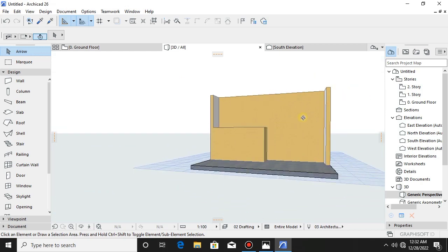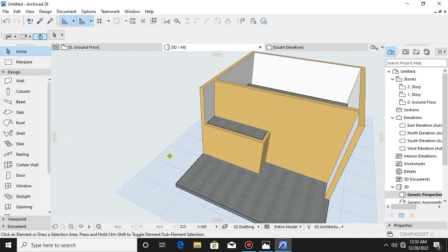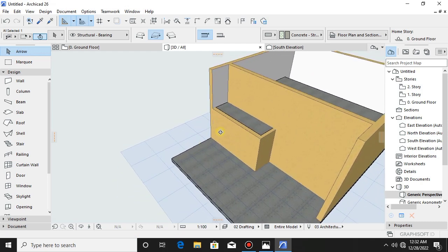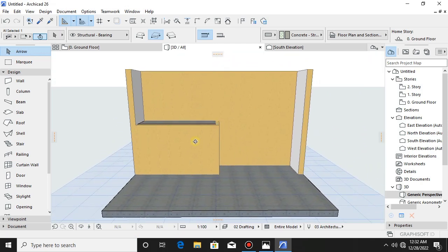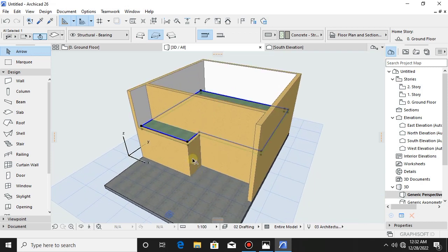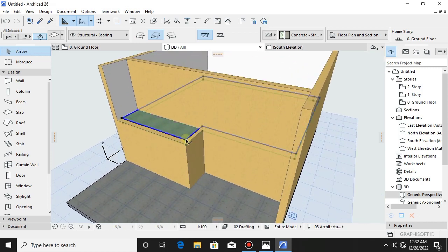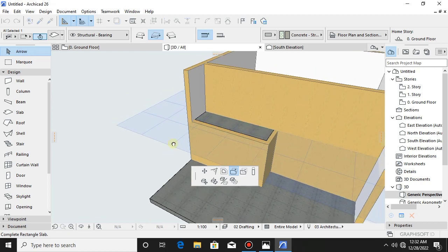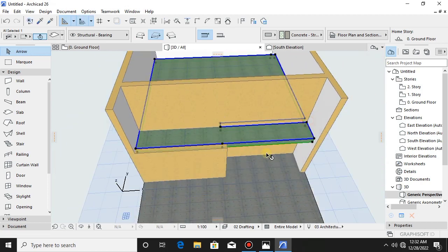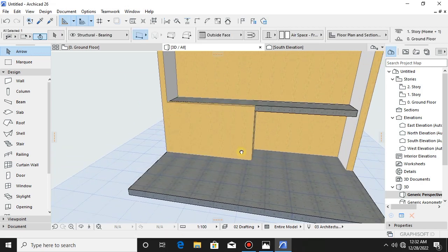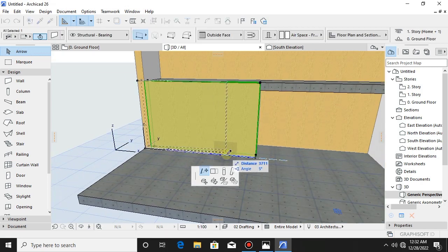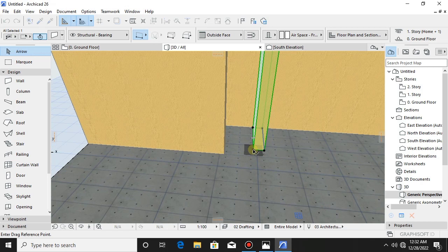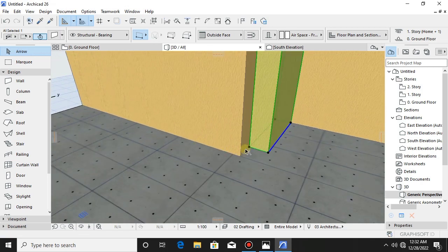As you can see, now we have a nice view of our incomplete facade. So we're gonna work out on the front. So let us extend the slab also on the right hand side to complete the balcony by using the adding tool. And make sure that our slab aligns with the wall. Now let's also duplicate the bottom wall by first moving it to make sure it's of the correct measurements. By moving it a meter to the left, align right there.